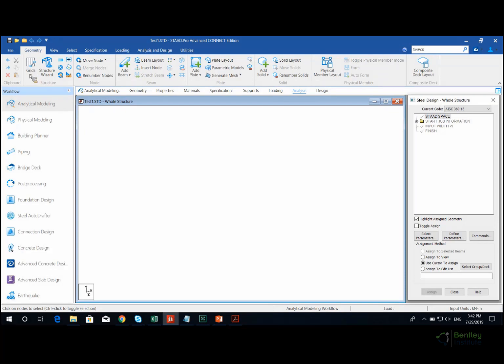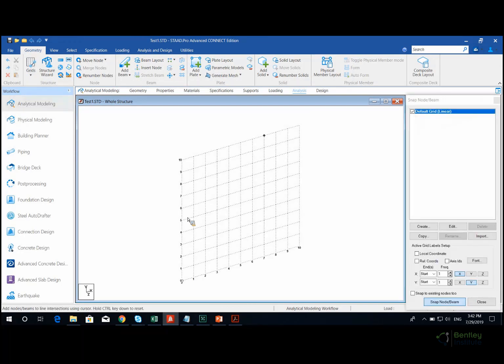So to create a building structure, you can either choose a beam grid, but it's a big building. It's a G+7, so lots of beams and lots of columns are there. If you create it by a grid, you have to perform translation and repeat, which will be kind of tiresome for you.